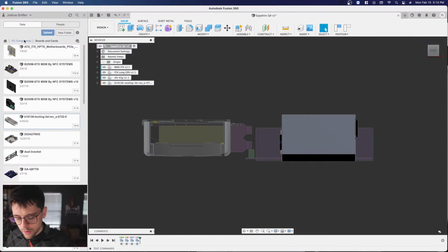I like 8 millimeters for custom cases for this reason. If you are designing a computer case for mass production with proper tooling, then you can pick your own standoff height, although I'll let you know that it gets to be pretty expensive for a console design. I can't go into that right now. It's actually one of the reasons the Mini is very special. It becomes more and more difficult. So you want to have the I/O shield and the bottom plate, which I'll cover later, far enough apart so when you're bending the metal, you get a nice, clean, crisp bend so the machine has something to grab onto. I found that 8 millimeter is pretty much the lowest you can go for really simple bending machines.